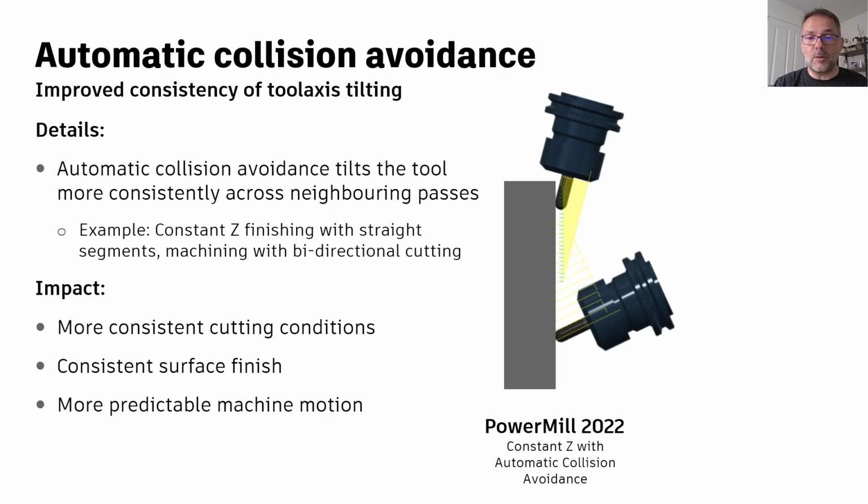Now, why is this a problem? The key issue here is that by changing the contact point on the cutting tool profile, we expose ourselves to varying errors in the cutting tool setup. Things like tool run out, varying levels of cutter push off, and even the dimensional inaccuracies of the profile of the tool itself. All of that can contribute to a degradation in surface finish.